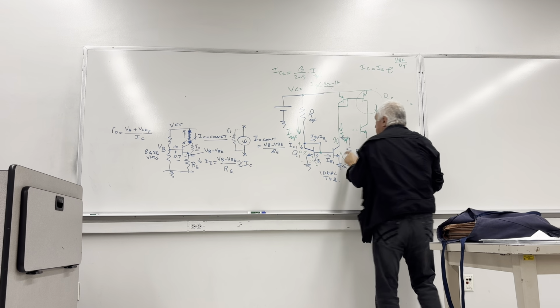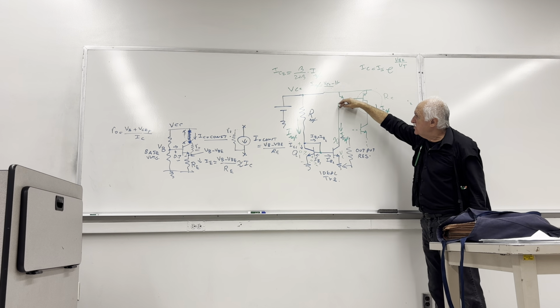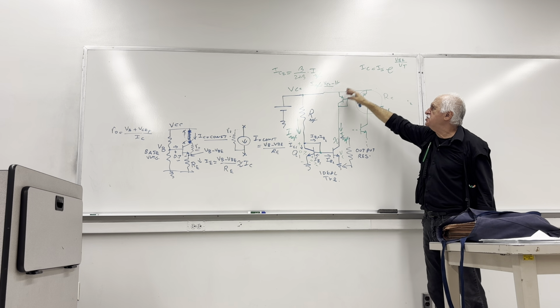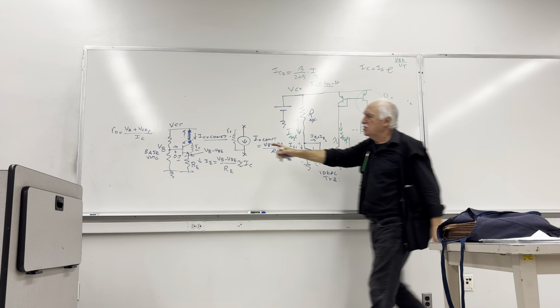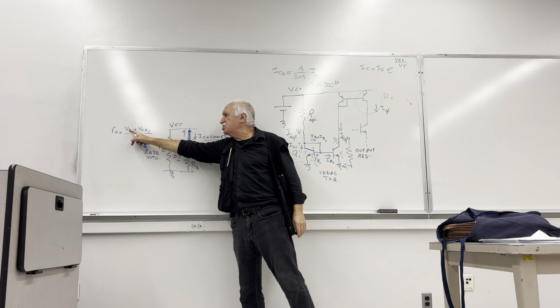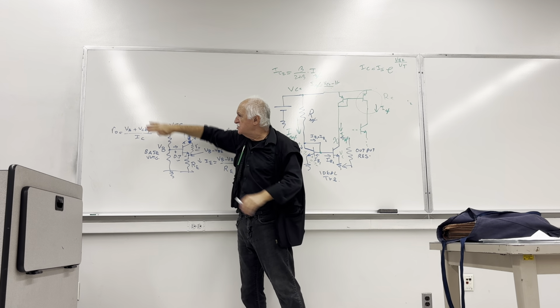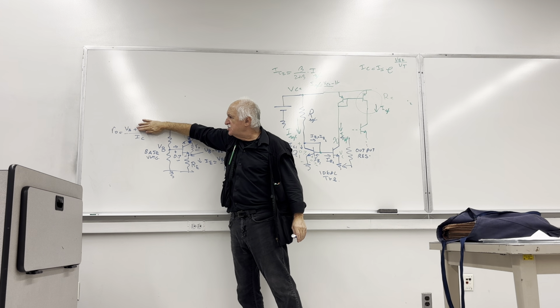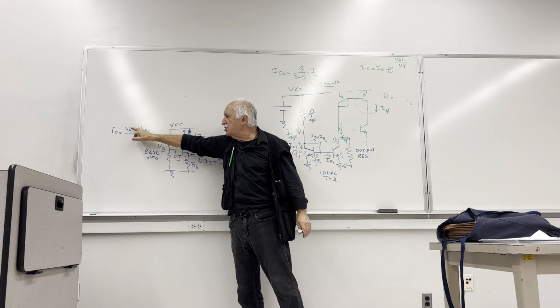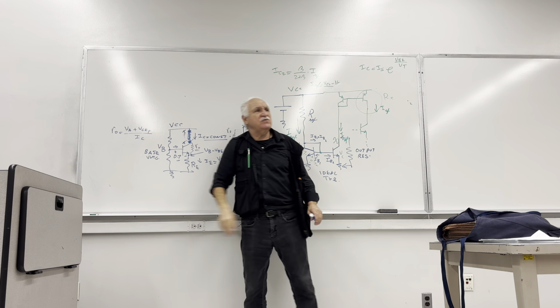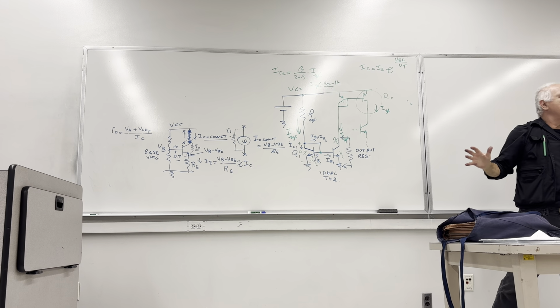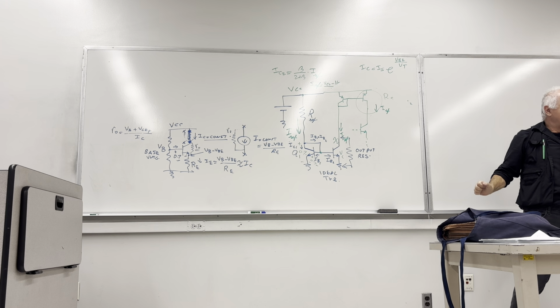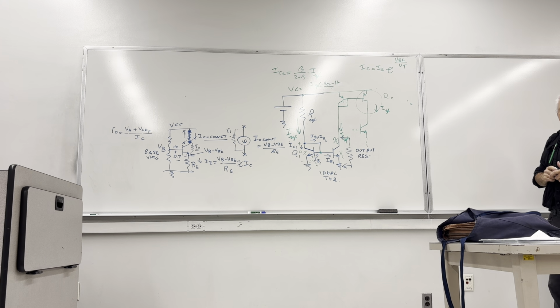VCE quiescent is the voltage from here to here, which can easily be calculated. It is not that significant because usually VCE quiescent is much smaller than VA. If you drop it, you notice that RO depends on the early voltage and the choice of collector current. So the lower you bias, the higher, or more ideal, a current source you can get out of the transistor.